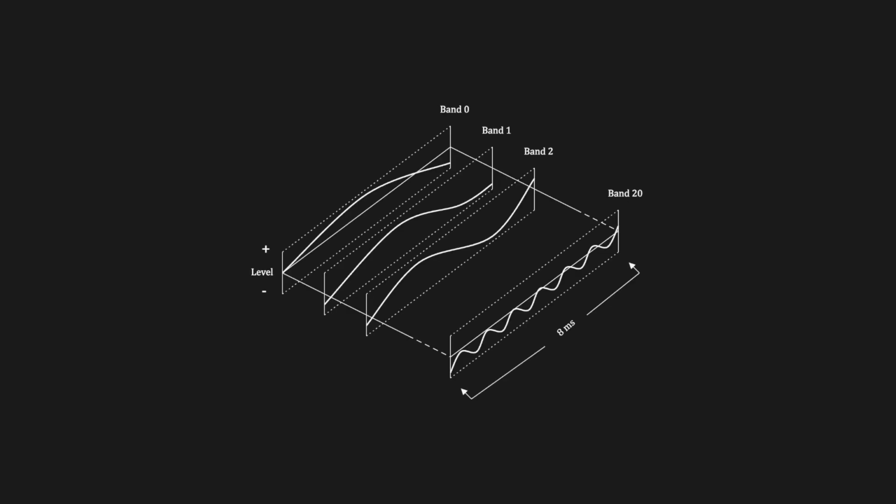The bit allocation for each subband is decided by a psychoacoustic model that analyzes what the ear can hear. This process is repeated for every new block of data, and the quantization changes dynamically, depending on how audible the sound and noise are. Different codecs may use various psychoacoustic models and bit allocation algorithms. During playback, the decoder reconstructs each subband and combines them through a synthesis filter bank to rebuild the full audio signal. A perceptual subband codec splits a short section of audio into several frequency bands using a filter bank.